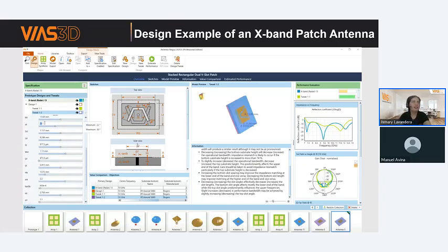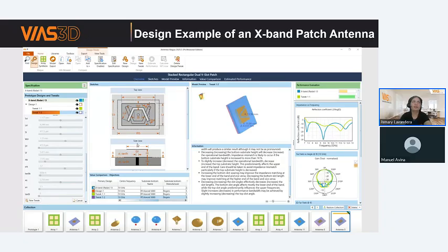And also I know that according to the description here in the information, decreasing the slot angle will affect the bandwidth. So I will be changing to the minimum value, because it is recommended to be between 22 and 30. And with that, I will estimate the new performance of my antenna.